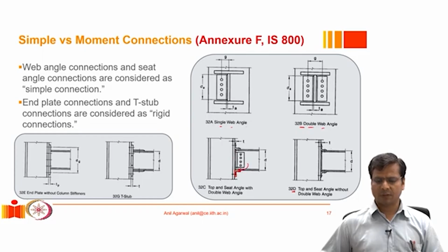It carries most of the load that is applied to the beam, transfers it to the column, and we typically have a couple of bolts here or a deep weld here to connect this angle to the column. Sometimes this angle can even be stiffened. We may put a stiffener inside this angle to help it resist the load more effectively. As you might realize, let me zoom into it a little bit.